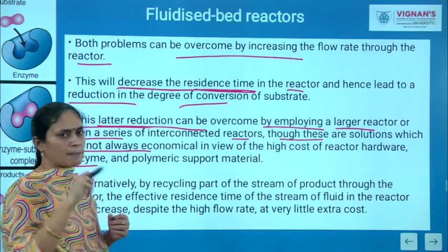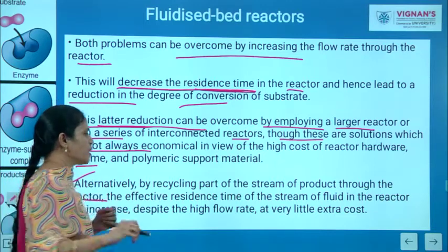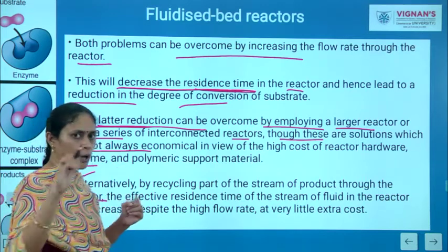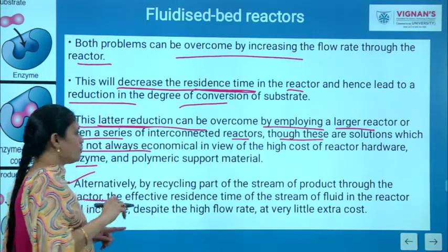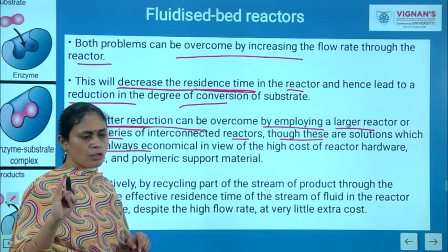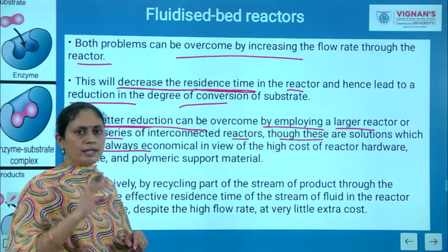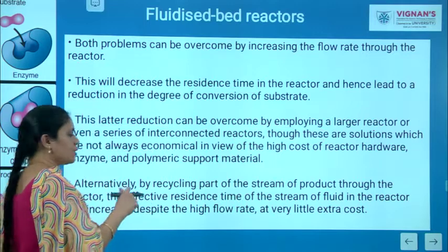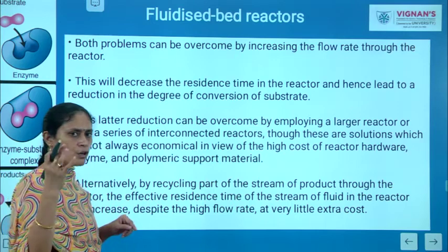Alternatively, by recycling part of the stream of your product through the reactor, the time of residence of your substrate along with your enzyme can be increased. So, either by increasing the size of your reactor or by implementing recycling, you can increase the time of contact between your substrate and enzyme so that you can get higher yield,